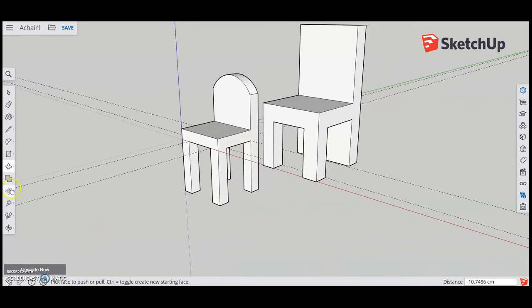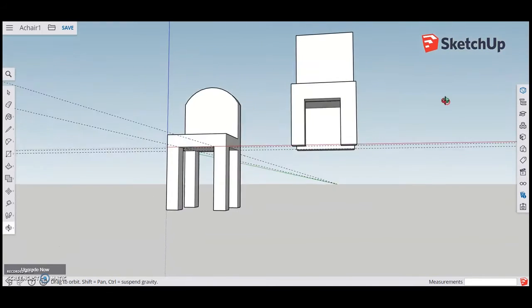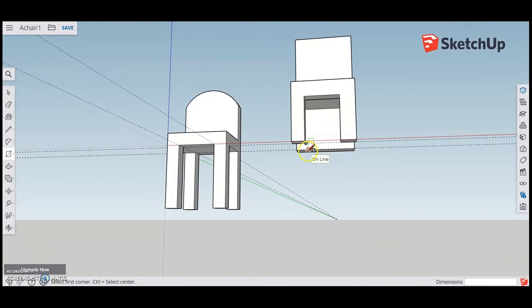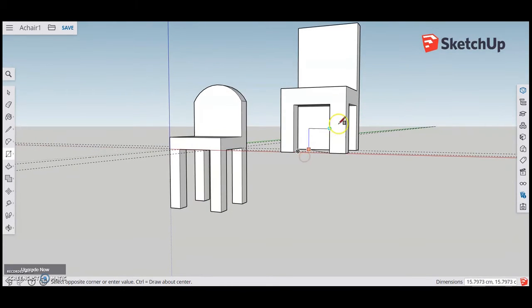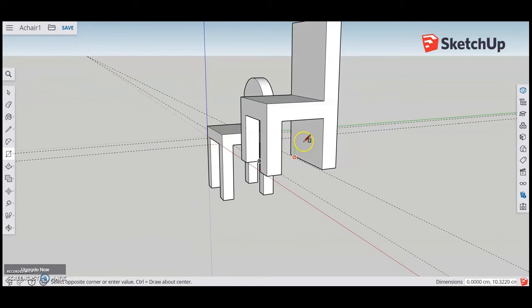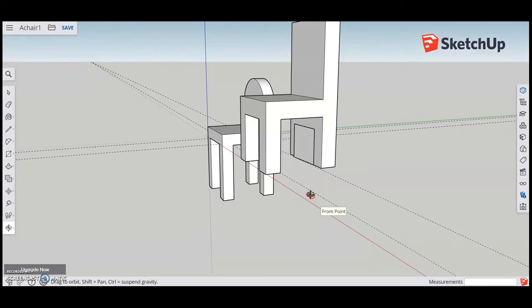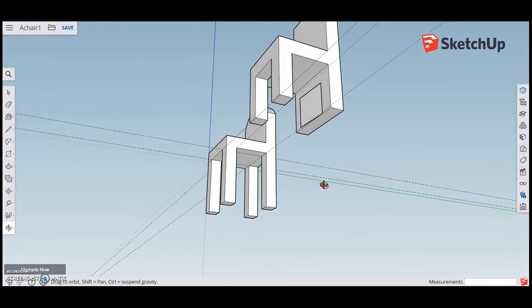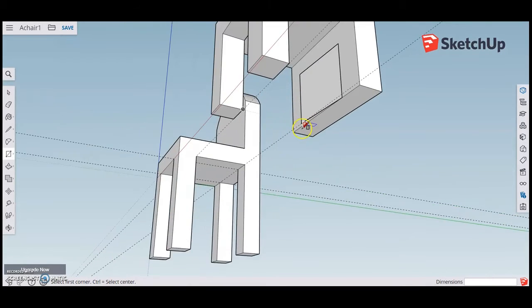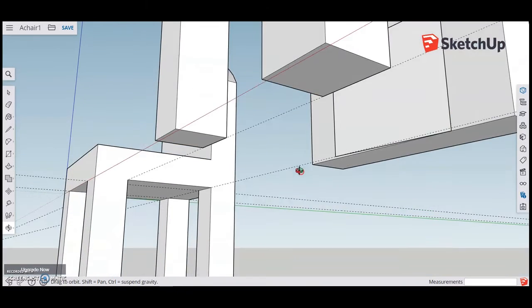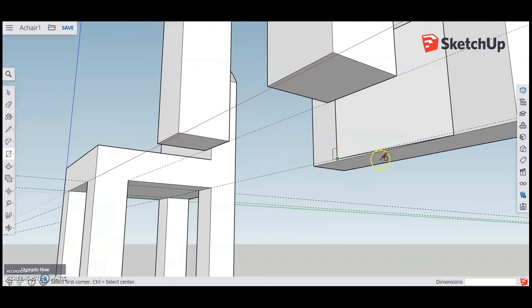And then finally, to get our last legs in place, we're going to grab that rectangle tool again. Again, this doesn't have to be perfect, but you can roughly infer from one point to another. And in this way, we're going to kind of draw this new shape. Now, it's important to make sure that it's drawn in the correct orientation. For our purpose, that means it's going to be on face on this surface underneath the seat. And you can see that what's happened is I made a mistake. It didn't work. And that's because our guide in place here from our previous model caused this to snap over.